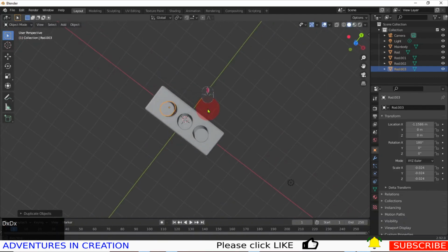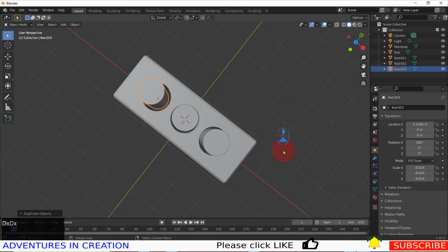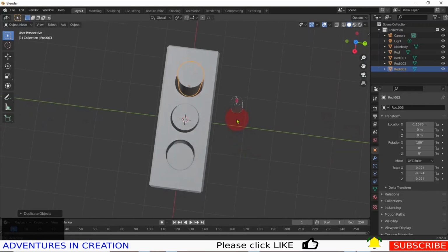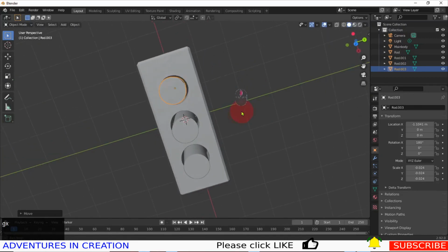And if I look from the top, I can see roughly where I am in terms of being in the center there. That one's not bad, that one's not bad. This one I think needs to move down. So to move something, it's just G for grab, and then X. And I can just bring it to this roughly in the middle there. That looks pretty good.